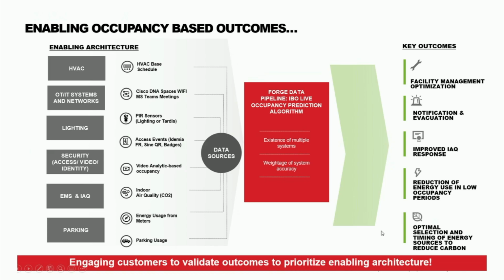So the more CO2 you have in a space, the greater the chance of carrying pathogens around the building as well. So there's another reason to monitor CO2. It's a very cheap way of identifying the likelihood of pathogen spread. But with indoor air quality, we want to make sure that where people are, their space is nice and breathable without risk to their health.